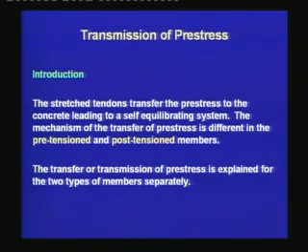The stretched tendons transfer the prestress to the concrete, leading to a self-equilibrating system. The transfer or transmission of prestress is explained for the two types of members separately. First, the pre-tension members.